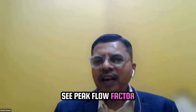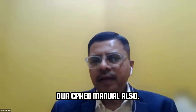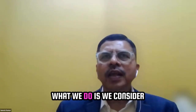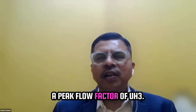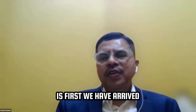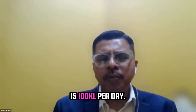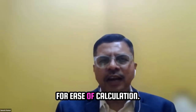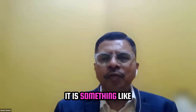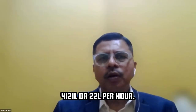See, peak flow factor calculation is again given in our CPHEEO manual also. But otherwise, as a thumb rule, what we do is we consider a peak flow factor of 3. How it works is, first we arrive at an STP capacity. Let us say my STP capacity is 100 KL per day. I'm just taking it for ease of calculation. 100 KL per day, if I divide by 24 hours, it is something like 4,121 liters, or 4,122 liters per hour. Okay.